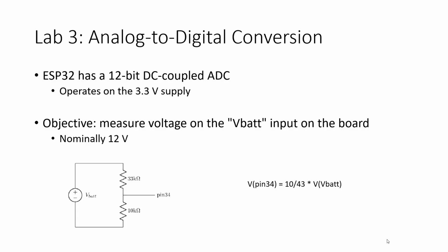So we're assuming that the chip is running at 3.3 volts, the motors are running at 12 volts, and so the battery must be 14 volts. The battery is 12.6 fully charged. The reason it went up to 14 is just because that's the highest voltage the voltage divider can support before it starts feeding more than 3.3 into the pin.